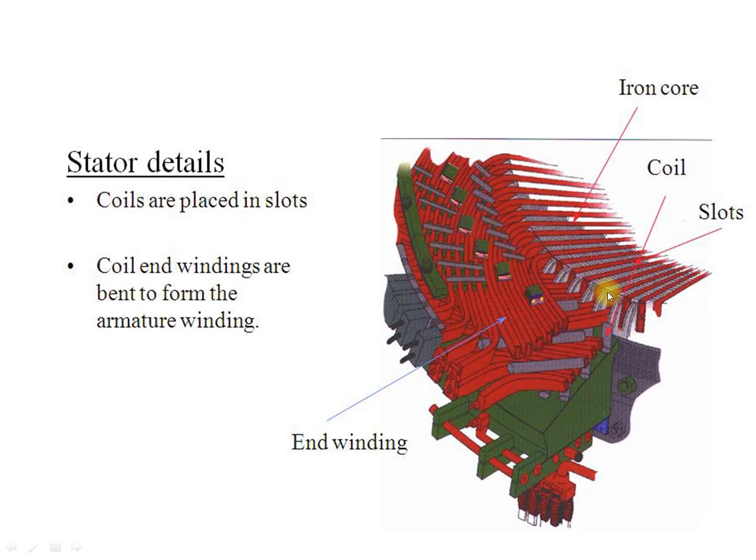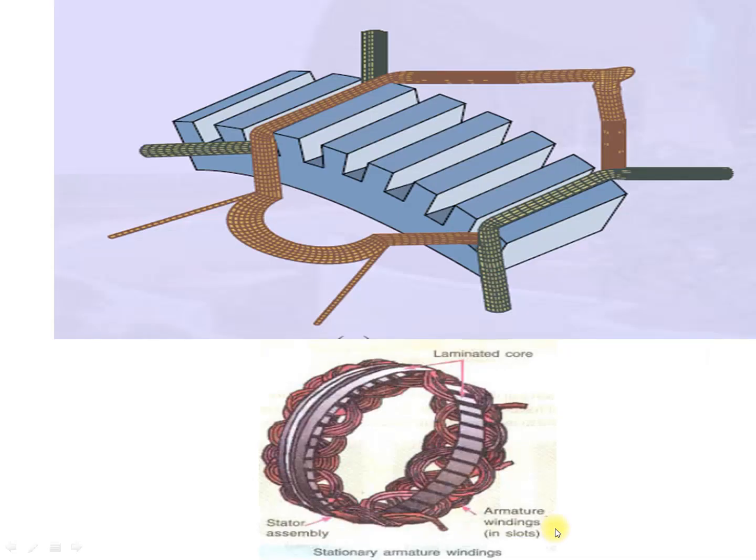Here we have the slots marked in blue, and on those we will place the coils, and the ends of the coils are connected together. They can be connected with the outer rings through the end windings, and these will be supplied with the three-phase output of this machine.